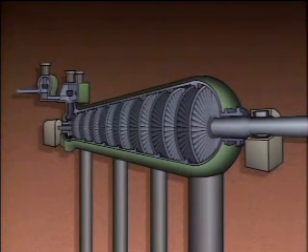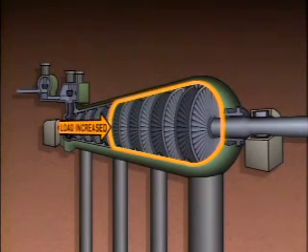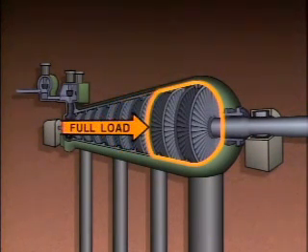To understand how these systems work, it's helpful to know how pressure varies in a turbine. The pressure inside a turbine varies with the load. At low loads, many of the later stages in a turbine may be under a vacuum. As load is increased, more and more of these stages start to operate under pressure. Finally, at full load, only the last few stages of the turbine may actually be under a vacuum.